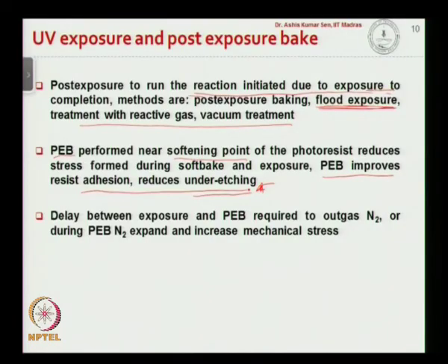So after you do the UV exposure, you do not go for the post exposure bake immediately; you wait for some time and then take it to the post exposure bake. It helps the outgassing of nitrogen, and it also reduces the mechanical stress.